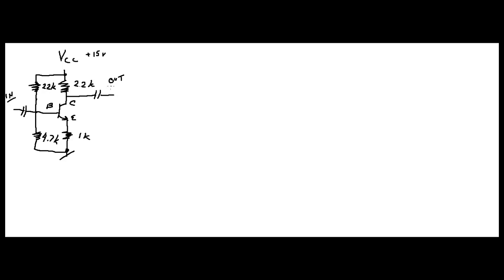So remember, when you write the circuit, basically the capacitors act as an open, like it's been cut, right? So basically this line here we can get rid of, and this input here over here we can get rid of, right?